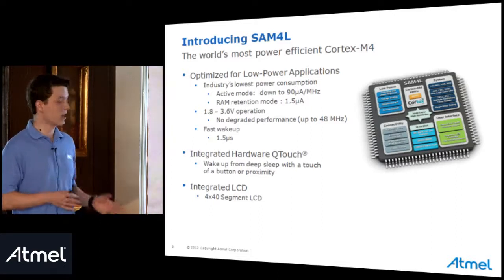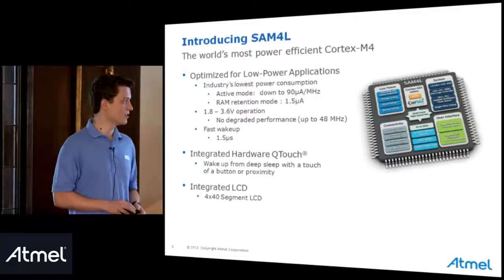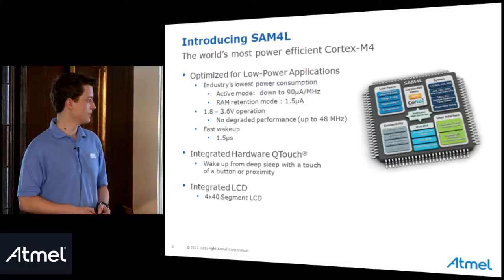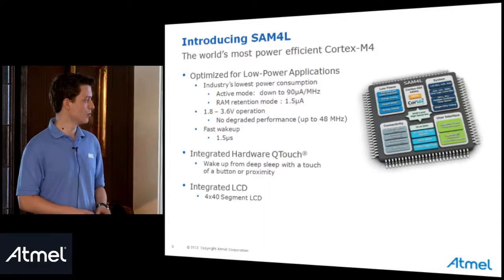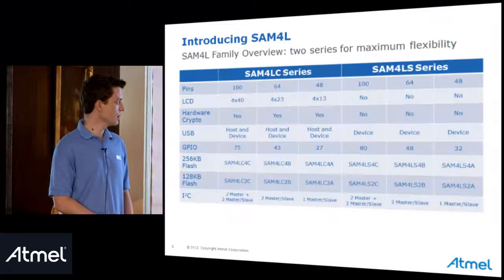This hardware QTouch is also built for low power techniques, as it allows waking up from deep sleep mode with just a touch. The next point is that we also embed a segment LCD controller, which can drive up to 4 by 40 segment LCD.